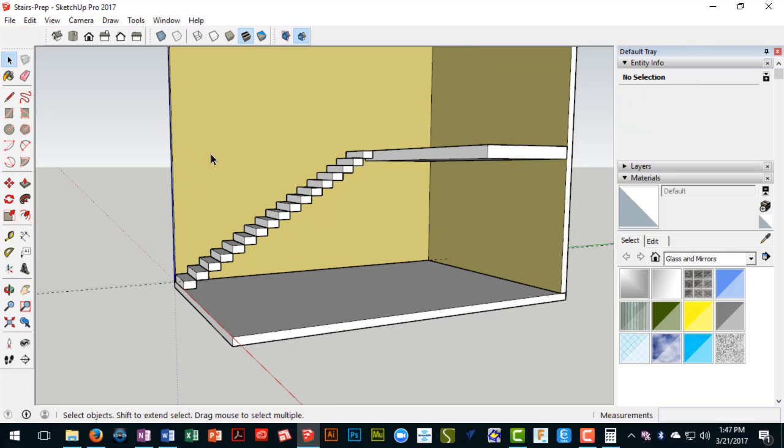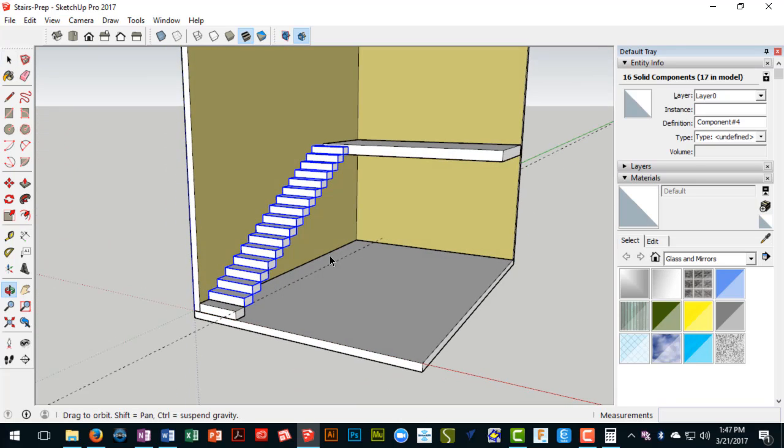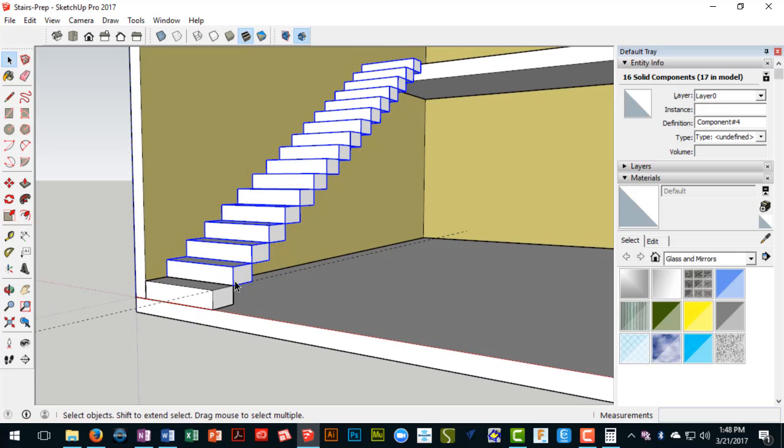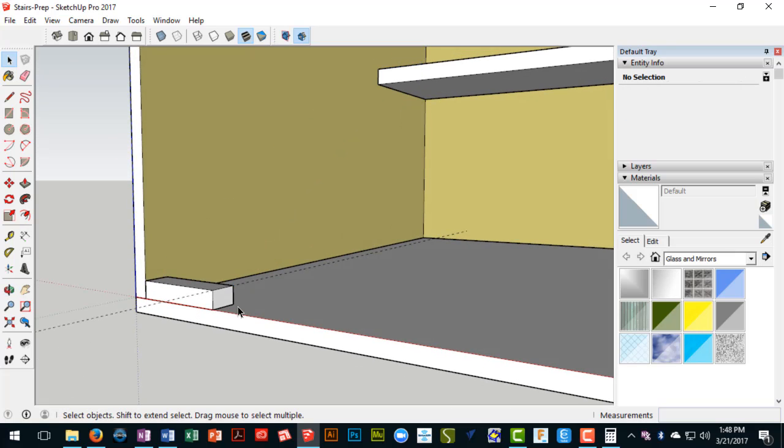So I specifically want to go from left to right, which means anything that I select, I have to totally enclose with this selection box. And I'm not totally enclosing that first riser block, and I'm not totally enclosing anything else. So I'm very easily getting all of these blocks instead of shift clicking on all of them. So now that I have them all selected except for the first one, I'll press delete.